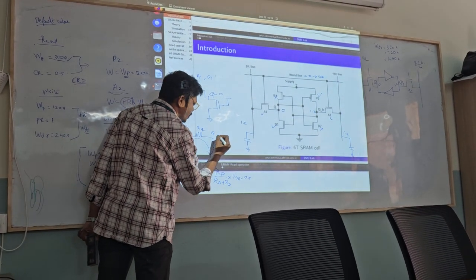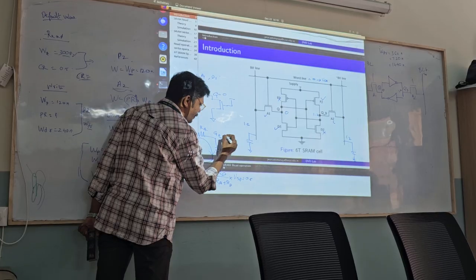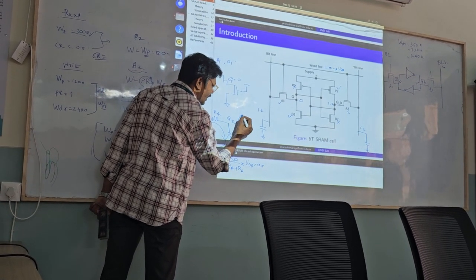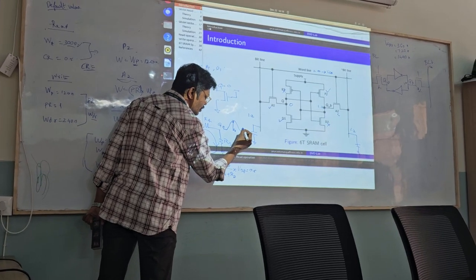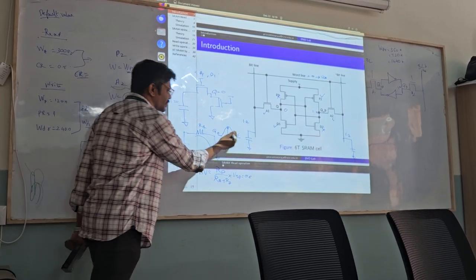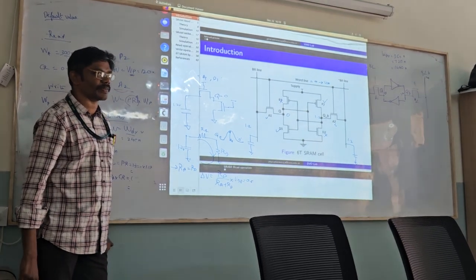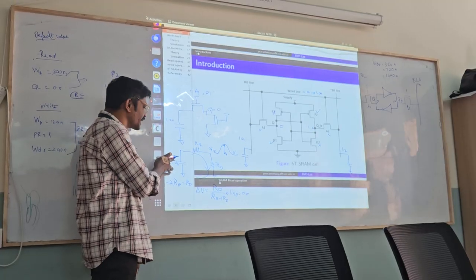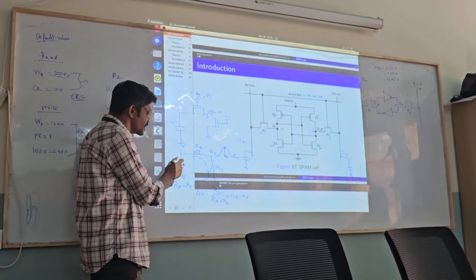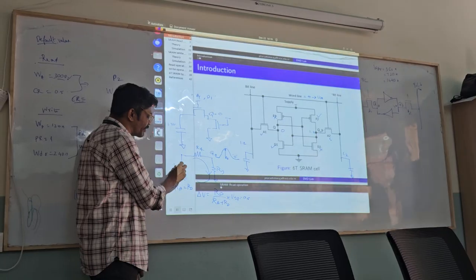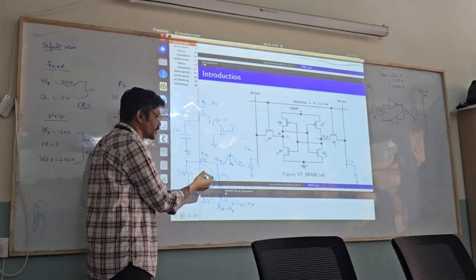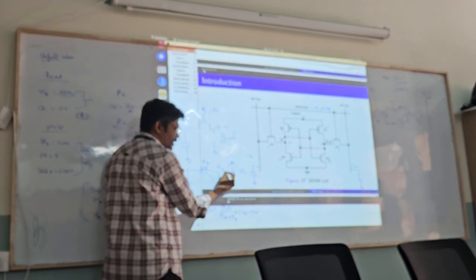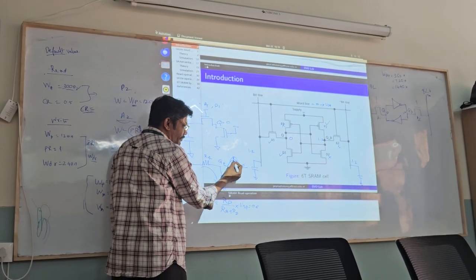This means from 0, it will have a bump, and this bump will reach a maximum value of 0.6. But after that, it will also get reduced back to 0. Why is this reduction to 0 happening here? Because it's a capacitor, it's not a fixed potential that I'm trying to fix here. Because of this capacitance, the capacitor will try to lose its charge as the current flows through this particular loop. Even though I mentioned that this voltage will go all the way to 0.6, it never actually does. So some sort of voltage will happen here, and we will try to reach this maximum.